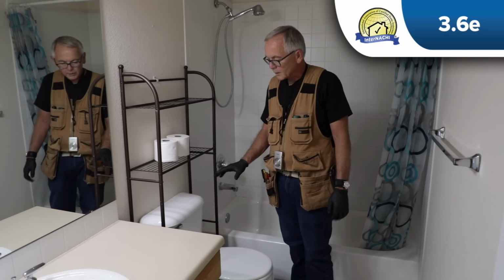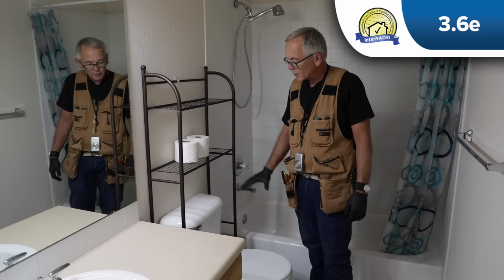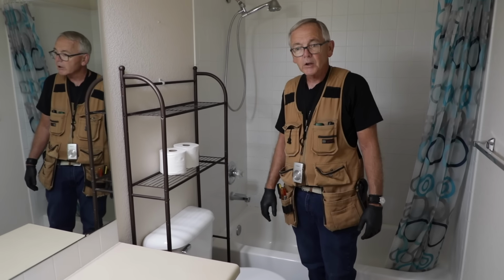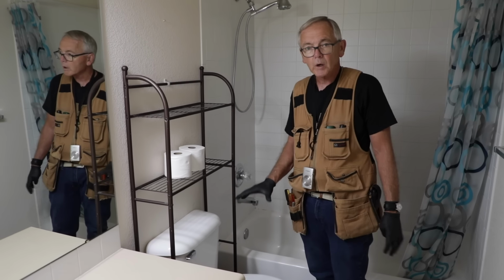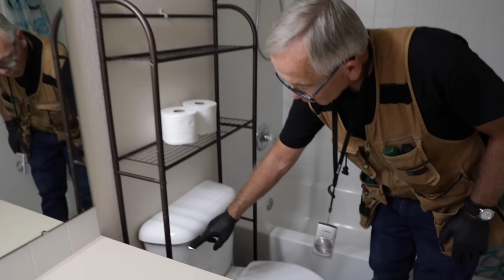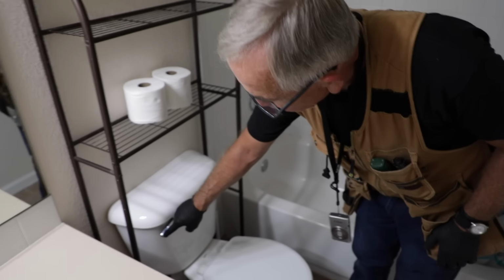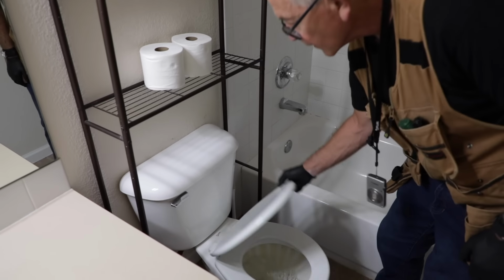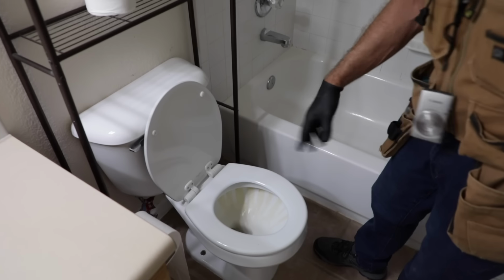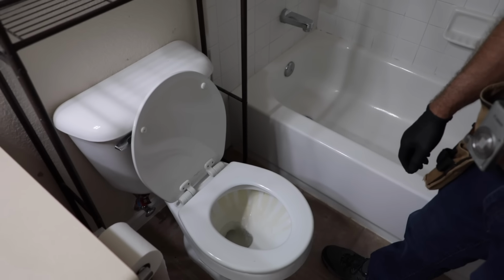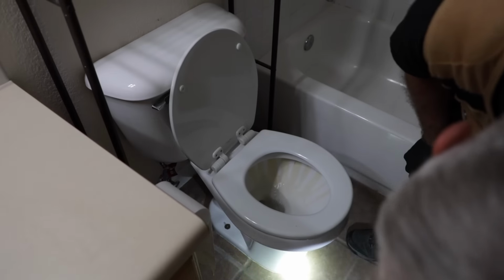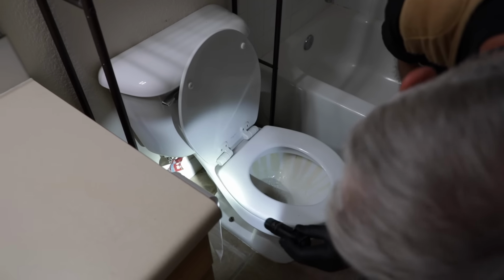Okay, we're going to move on to toilets. We're going to be just inspecting for proper operation. And for the sake of this video, we are just going to show you just one toilet in this home. So we're just going to go over here to the lever. Just operate it normally. Look for proper drainage. You know, we can look for any potential leak around the base or around the supply valve.